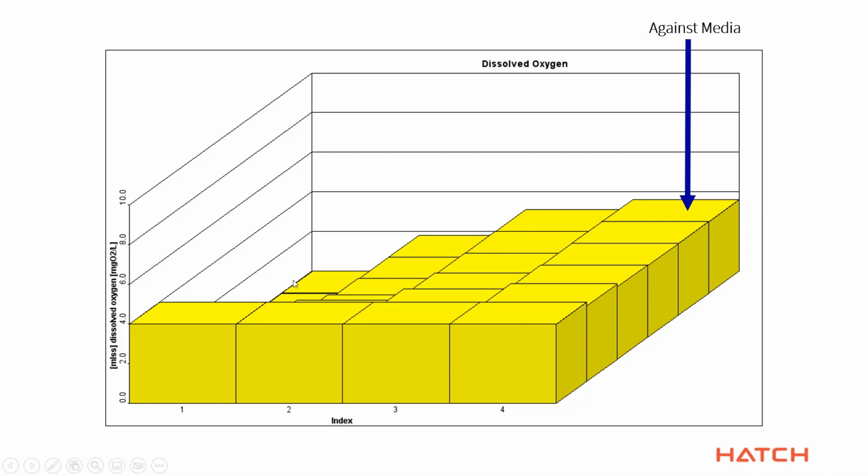So if you were to look in behind here, you can see that it's quite anoxic on the inside in the first reactor, meaning, of course, that there's a huge amount of biological activity happening right up front where all the substrate and all the ammonia and everything is. So as per usual, you expect more biological activity at the front of the tank. And we're diffusion limited on oxygen here is what this is telling us. Less so in the second reactor and third and fourth and so on. So we can see that it catches up with the rest of the load by the time you get to the end, such that we get pretty much full penetration of oxygen here. It's 3.5 or something at the back here, even though it was close to 0 in the first tank.